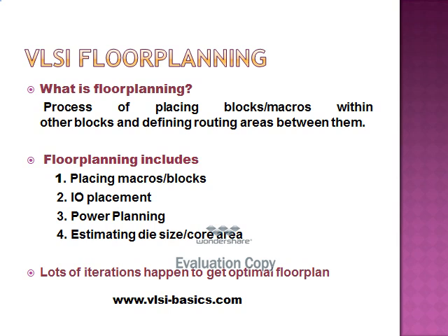Floor planning is the process of placing blocks or macros on die or within other blocks and defining routing areas between the blocks or macros. Floor planning includes macro or block placement, pin placement, power planning and power grid design.